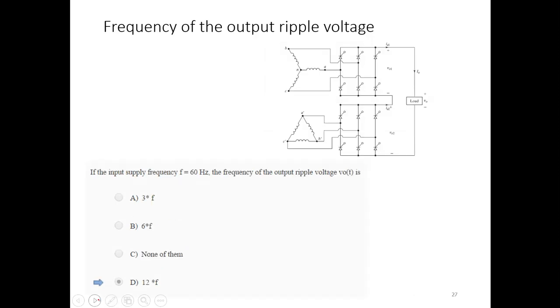Now, many times you put them in series or parallel. This is connected in series, selected to increase the voltage limit. If this converter can give you 1 voltage, the other one gives output, you get to double the voltage you can have. Sometimes you connect them. Now, in this particular case, there will be like 12 pulses. This will be 6, this will be 6 there. That will be 12 pulses. There will be 12 pulses you expect in the output.